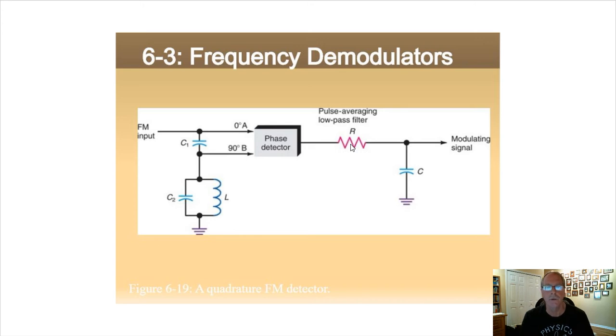Now, we talked previously, a few weeks ago, about FM being indirect, or phase modulation being like indirect FM. It's hard to tell the two apart, and this phase detector doesn't know the difference between those two things. It sees a difference in phase as FM is happening. As frequency modulation happens, you get this phase difference between the two on a time-to-time basis. At one period of time you get one phase relationship, at another period a different phase relationship.